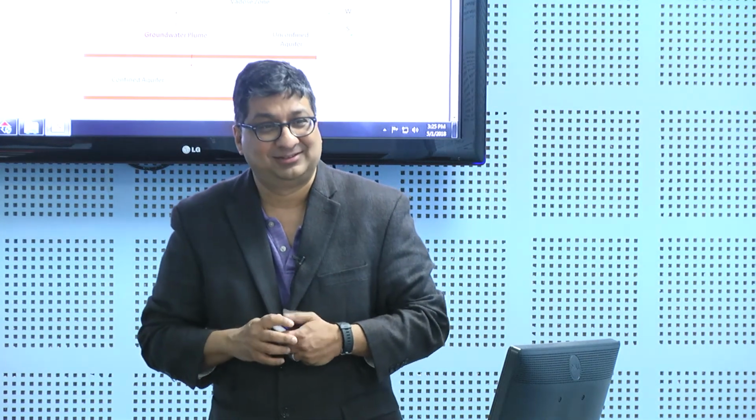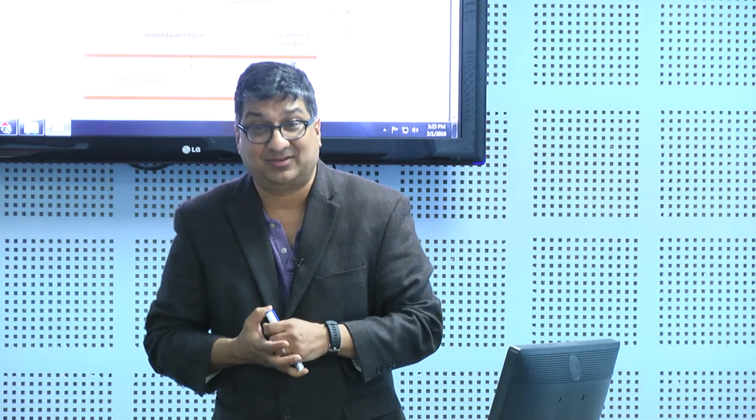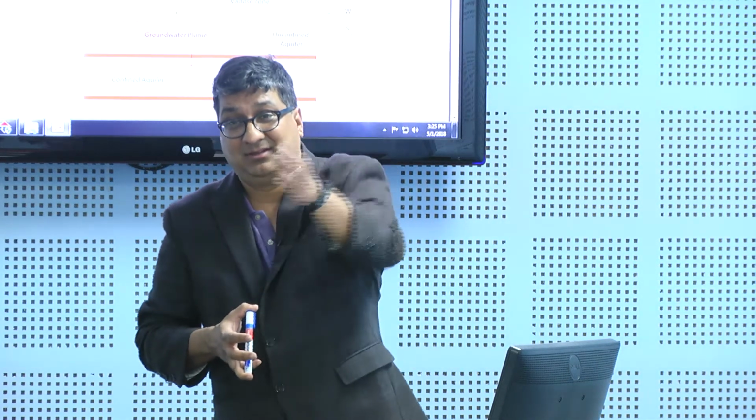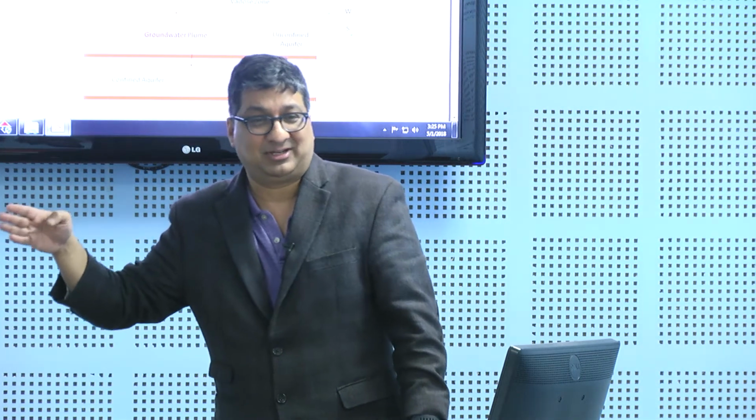Or not? Okay. In some cases, if I were to put in a certain treatment technology, it'll take me about 100 years to clean that water to drinking water standards. Okay. Well, what do we know about cleanups? They usually have an exponential curve, which means I can bring it to 90% of the drinking water standards within 10 years, but that last 10% will take me another 90 years to get there, because of the way